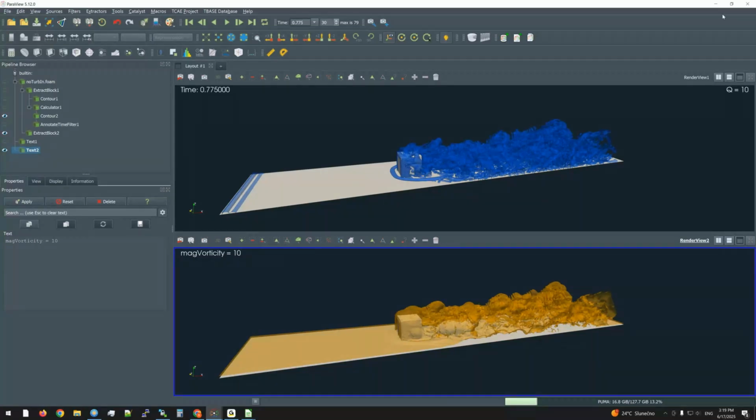All of these are connected with visualizing the results, but with ParaView you can also post-process the integral values. For example, you can simply compute the flow rate in any section of your domain you need.